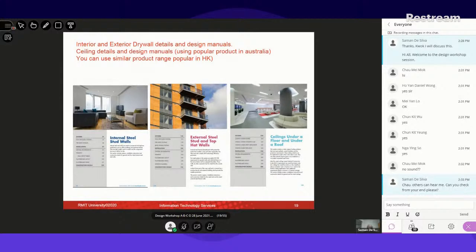The other thing is the ceiling, which is what we normally call a false ceiling. We don't go and paint the soffit or the underside of the slabs, because there will be lots of services like water supply, cooling ducts, electricity, sewer lines and pipes.